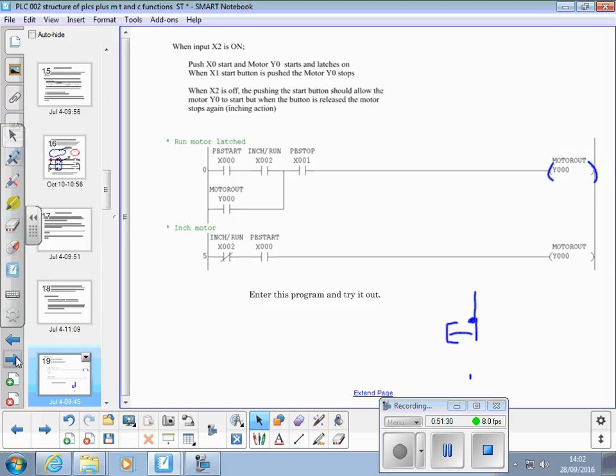Otherwise, you imagine that stop button sitting there as a normally open stop button, like this, right? Sitting like that, with the machine running, right? That wire falls off there, so it's not connected anymore. Someone wants to stop the machine, they hit that stop button, it's not going to stop. Because it didn't fail safe.